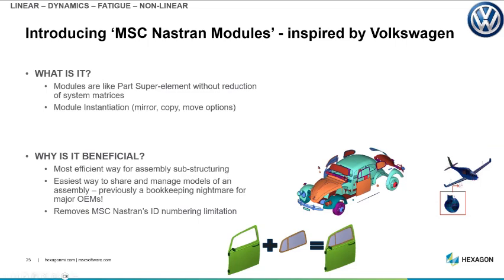What superelements do is an additional step where it actually calculates the simplified behavior of each of these parts, and then we combine them. Even if it can do that, what we'll by default do is to simply not include the reduced or the simplified behavior. It can be a full nonlinear part. It's simply an additional copy. So think of it in a way like parts or instances in a CAD program.